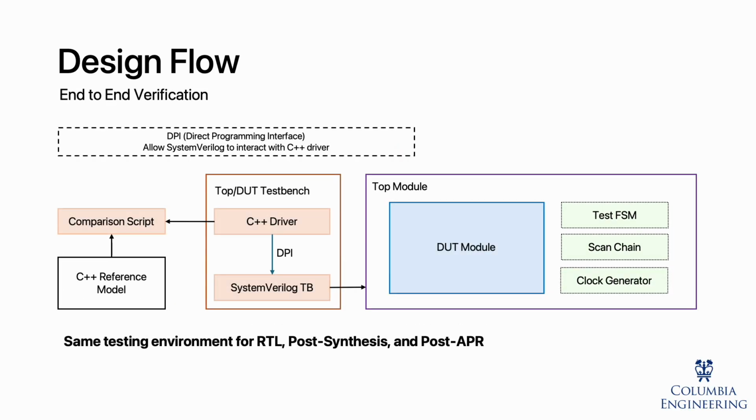After preparing all the individual blocks, we conducted end-to-end verification at the top level. The core of this process was a test bench composed of two parts. One is the C++ driver that handles the model file processing, UART command generation, and output image collection. It also forwards the hardware-generated output to a comparison script that validates the image against the golden model. We also reused this driver in our final demo.